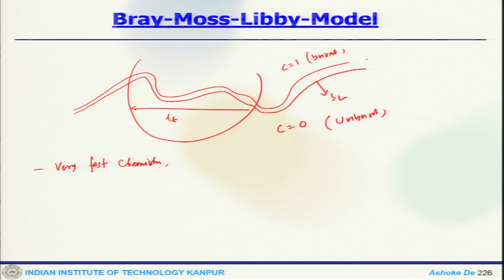That means the flame size, this is the LF, the flame size LF is less than LT and less than eta also. Now, another thing is that fuel conversion happens only in the area of the thin flame front. So, that could be in the flow field, burned mixture or unburned mixture, or intermediate states are very unlikely. So, that is another assumption which is there. You can define a flame front. So, in this thin flame front only the fuel conversion actually takes place.